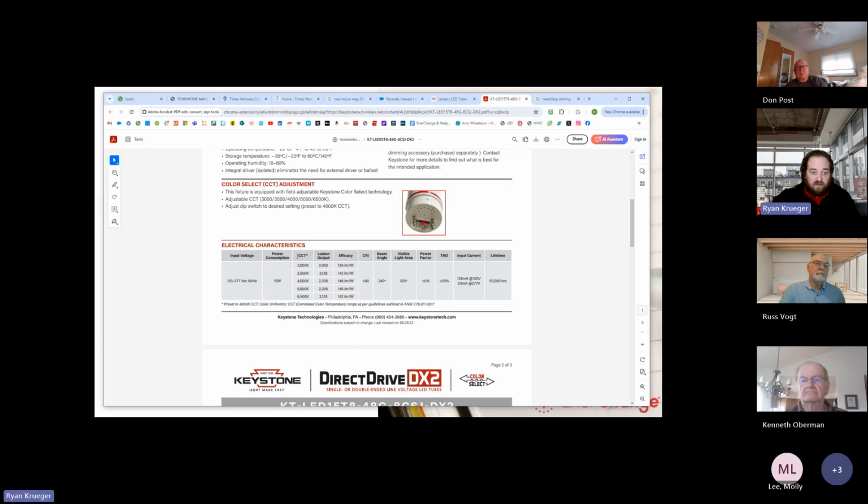On this, it's referred to as CCT instead of Kelvin temperature, which is why knowing all three terms is helpful. The lumen output slightly changes depending on the Kelvin temperature. Granted, it's not a lot, but in certain applications, it might be prevalent. How they've determined the efficiency of LED for the last 10 years or so has been lumens per watt.